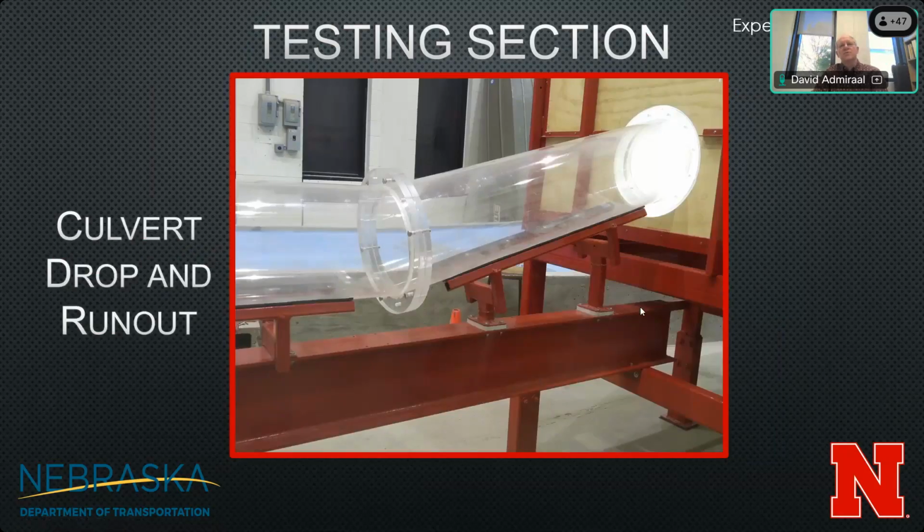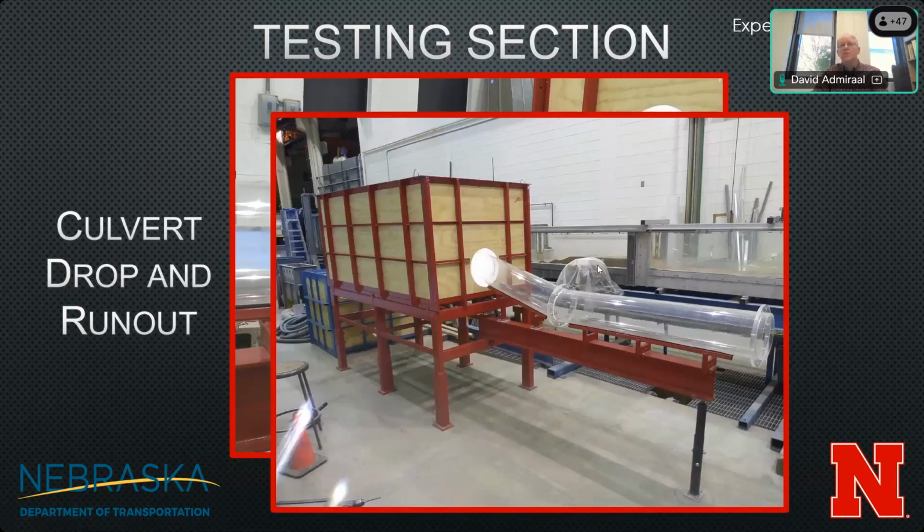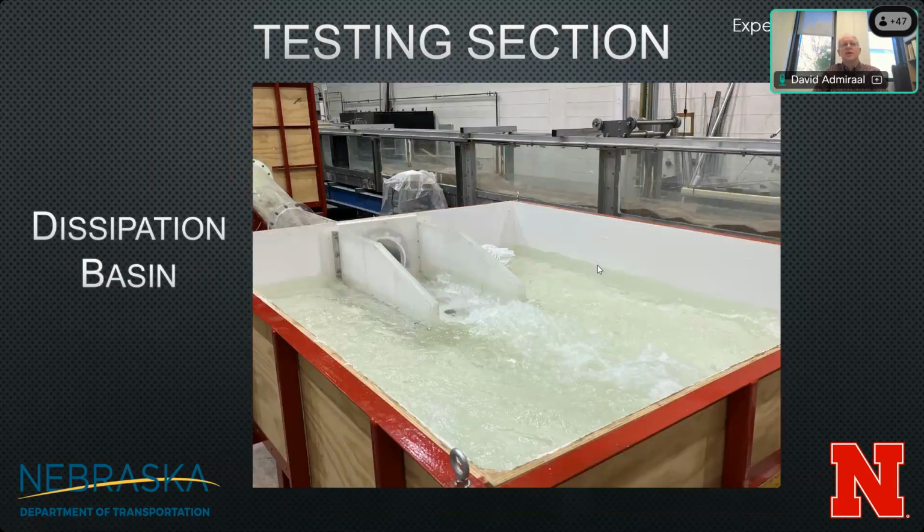So here is our drop structure. Just a little closer look at that. There are actually little piezometers in the bottom of this that you can't see. They're not in there yet in this picture, but they're pressure taps for measuring depth. We have the same thing throughout. Here's another look at it from the side. And then this is after we put it all together. So now you can see the tailwater basin's in place. Here's our dissipation basin. Here's our runout section, and we've got water coming out of this.